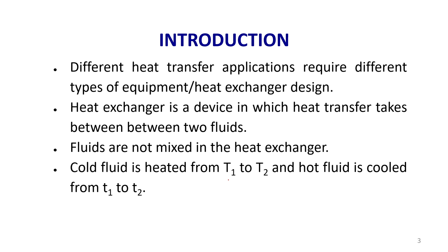When we say two fluids, as I mentioned before, it can be liquid and gas, or both can be liquids or both can be gases. So, here there are 4 temperatures involved. One is the inlet temperature of the cold fluid and its outlet temperature, and the inlet temperature of the hot fluid and its outlet temperature. So, two fluids, one inlet and one outlet each, that makes 4 temperatures.